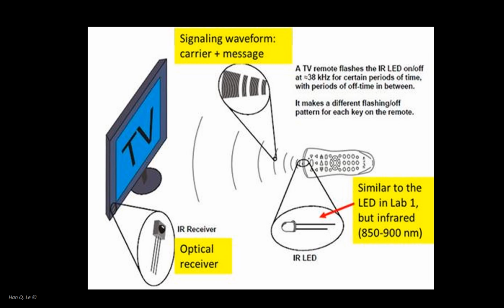The remote control sends a message to the appliance using an infrared light beam. It uses an LED transmitter. The message is received by an optical receiver, ubiquitous in all entertainment electronics, which includes all the subcomponents integrated in a highly compact, inexpensive package. What is to be built in Part B is equivalent to this device, and the circuit will be used to detect the remote control signal amplitude modulation, which is usually around 40 kHz or so.